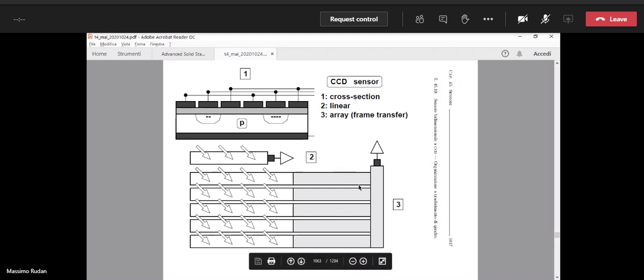More generally, the frequency of the vertical CCD is a multiple of the frequency of the horizontal CCD, and the multiplying factor is the number of lines of this architecture. This architecture is not unique. There is another possible architecture that we shall see in the next hour.